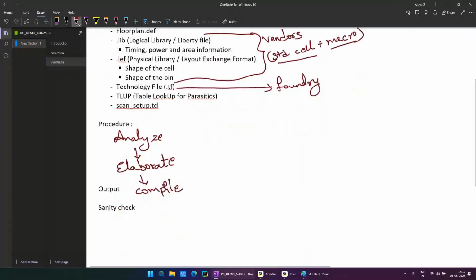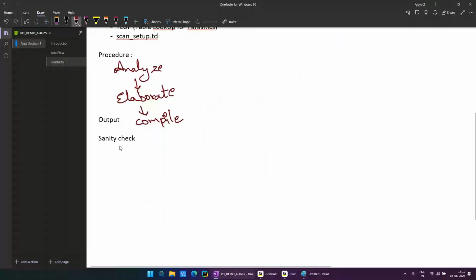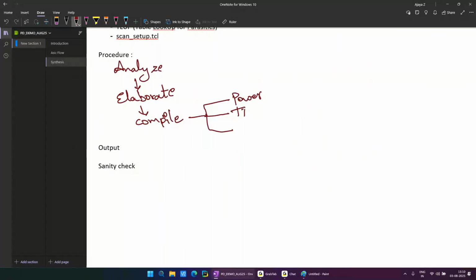So majorly there are these 3 different steps for the synthesis flow. If we execute this, your synthesis is done. But whether the optimization is as per my requirement or not, and if it is not proper, how do I make it more optimized? That is what we have to do. As I said, we are going to be performing the optimizations. Optimizations will be happening in this particular compile stage for your power, timing, and area. All this gets optimized in this compile stage only.